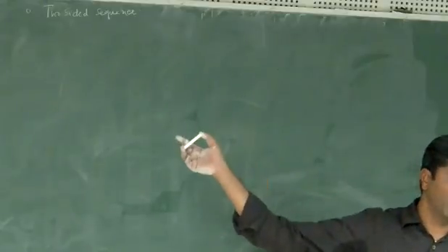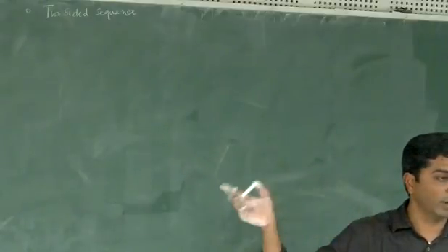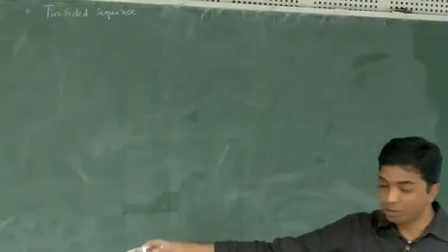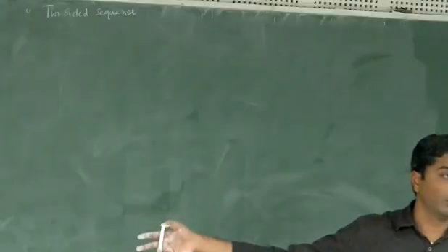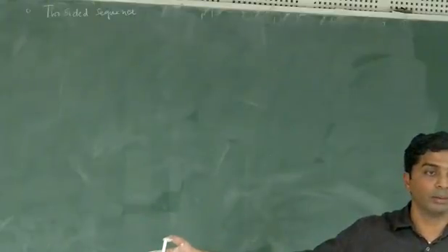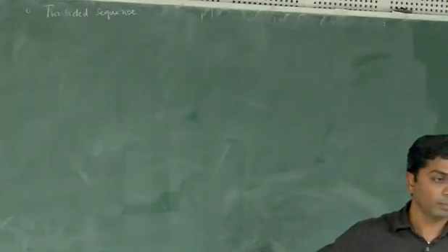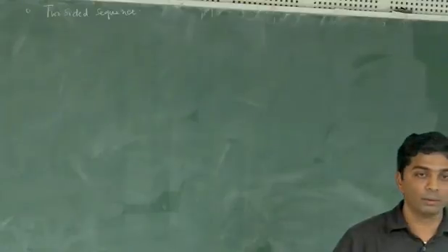So I can always write a two-sided sequence as a combination of a left-sided sequence and a right-sided sequence, right? So we know from the previous two results how the ROC is going to be for a left-sided sequence and a right-sided sequence, correct? And so when you take the intersection of these two, it has to be above something and lower than something, right?